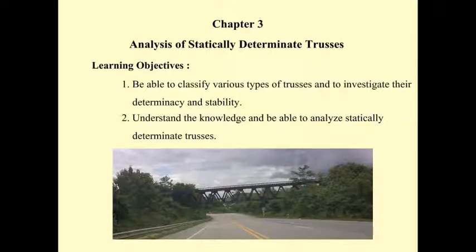One is the method of joints. We cut the joints and we draw the free body diagram, and we use 2 equations of equilibrium to analyze the joints. And we cut joint by joint, and we will get all the unknown forces in the members of the truss.